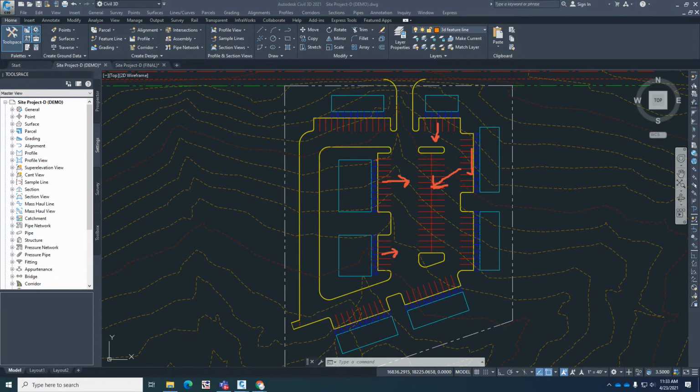So that's going to be your design. How are you going to do this? There are so many ways of doing this. I really need you to experiment and try it. More than likely, you will do it one way, it might not work, you might have to adjust it, and you might have to adjust that again. So it's a process. The design process is not very easy. Usually, you don't get it done on the first try. Usually, it takes a couple of tries. Okay. So those are the things that we need to do here. Once again, 0.5% minimum in the parking area, no more than 5% maximum.